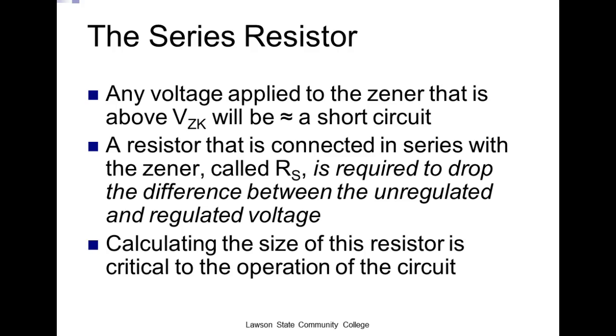If you put a resistor in there that's too small, you're going to burn your Zener up. If you put a resistor in there too big, you'll go below IZK and you'll go out of regulation. Won't hurt the Zener, you just won't regulate anymore, right? Everybody understand that? What formula are we going to use to calculate R? R is equal to V over I.